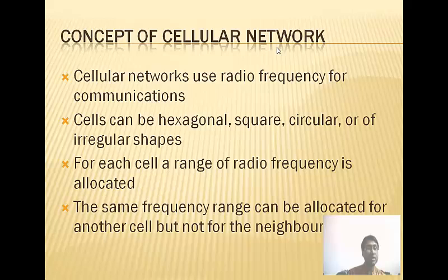I think the same radio frequency range can be reused in another cell, but one thing that has to be remembered is that you cannot use the same radio frequency range in neighboring cells. It can be used in a distant cell.